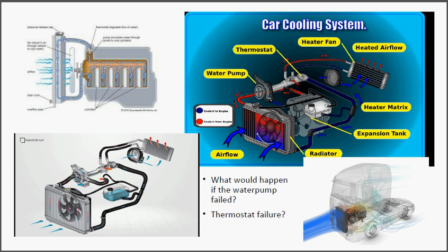Yeah, but it would be very slow, probably not enough to keep the engine running in good health, and I wouldn't try and test it out. So if your water pump ever goes down, get yourself to a garage and have it changed, or change it yourself. It's an important piece of kit in your car, so it's important to push the water through the radiators and through everything else, so you can't rely just on natural convection.